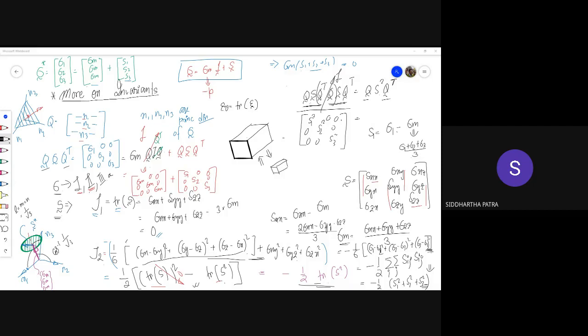Okay. Now, if a certain stress value, let's say the magnitude of the deviatoric stress tensor, were to remain within a certain limit for the structure to remain intact, or to not have any plastic deformation, I can represent that by a circle on the deviatoric plane. Okay, and that lets me have an idea of a yield surface. So that's what we'll do in our next class, talk about yield surfaces.